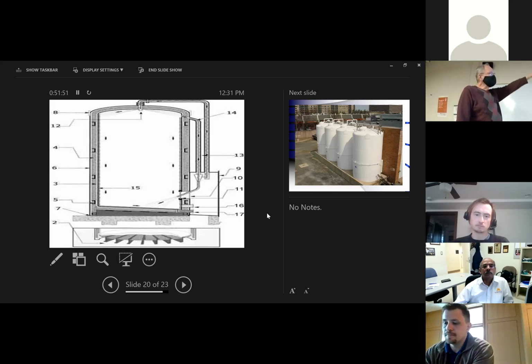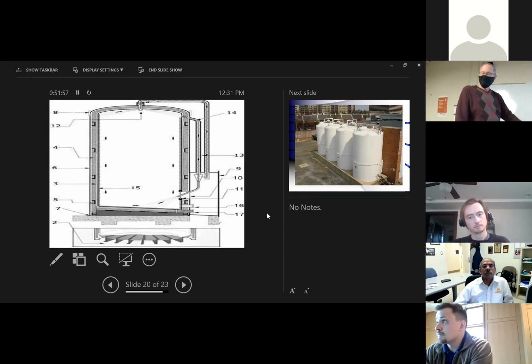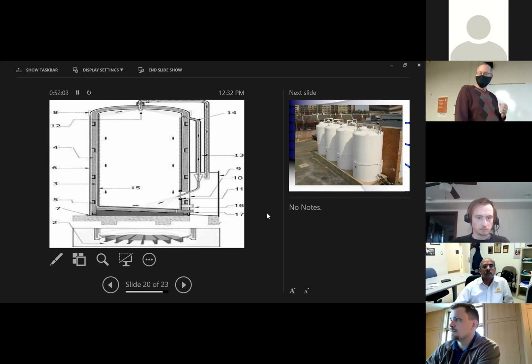But if you notice that number 14 there, that's your air equilibration. As you suck out, you need to bring air in to replace that volume inside. It's bad enough to suck in a bulk truck. Imagine sucking in a 100,000 gallon silo tank, crunching it up. Just think of taking an empty soda can and squeezing it. It crinkles real quick, and that's what can be happening in here.